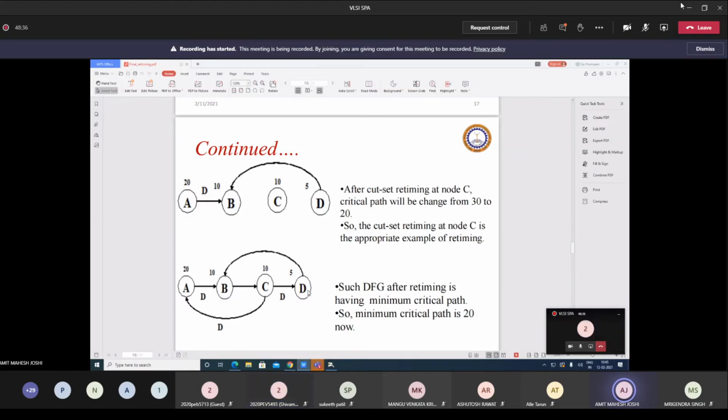If you remember, we applied the retiming vector formula, through which we wrote down a theorem that in a loop the number of delay elements before and after retiming should remain the same. Yes. And fundamental for that is, if it is not the same then your functionality would change. Yes, any doubt?